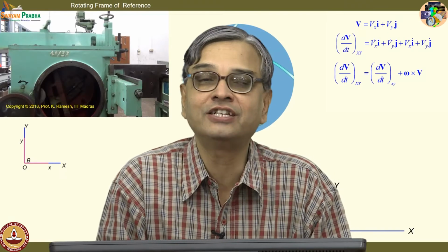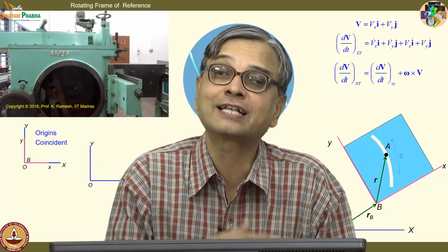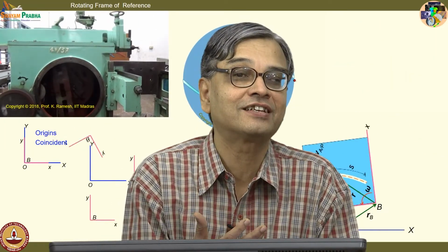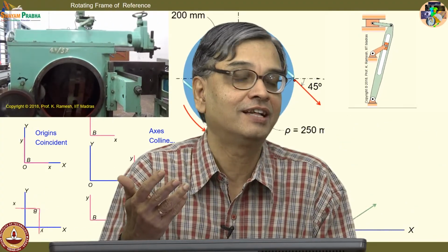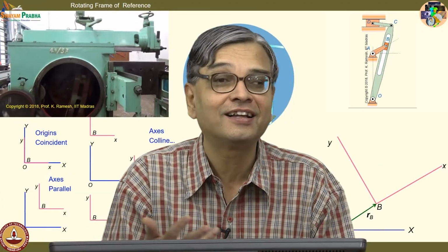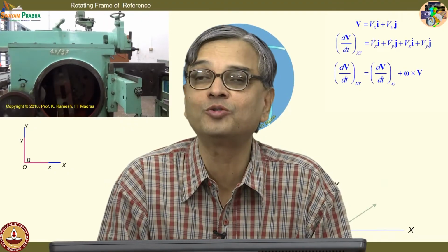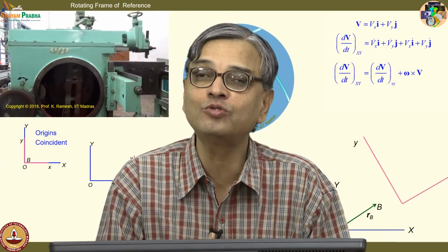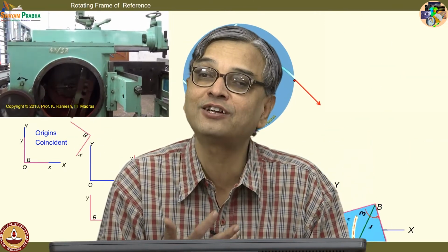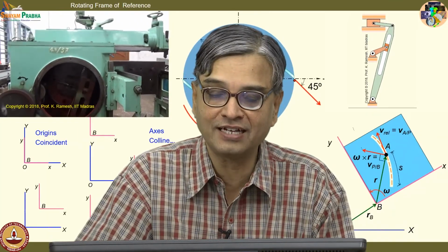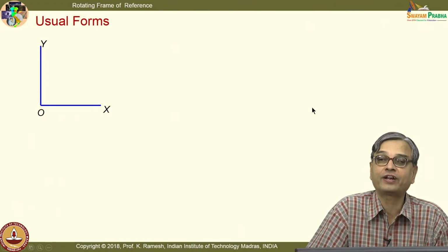Okay. But from an engineering perspective, if you are designing a theme park ride, you are expected to calculate the accelerations a person would experience when he sits in the cockpit and moves through it. It cannot exceed certain recommended levels given by organizations which do research on human safety. So, if I have to do that, I necessarily need a rotating frame of reference for me to start with and do the analysis. So, there is a class of problem that requires use of a rotating frame of reference.